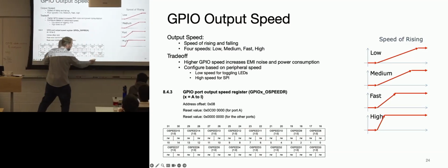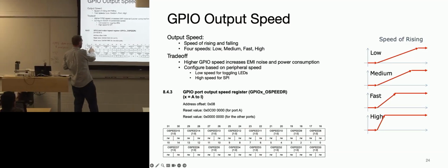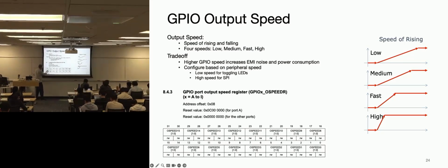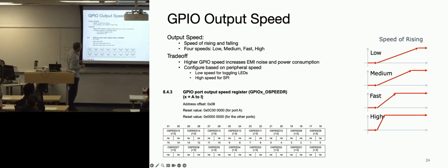Here's the 0th pin up to the 15th pin, taking 2 bits each. The data sheet is saying this is read-write, and this is the order 0, 1, this is the concatenation, up to the 15th pin in this register, or that peripheral.